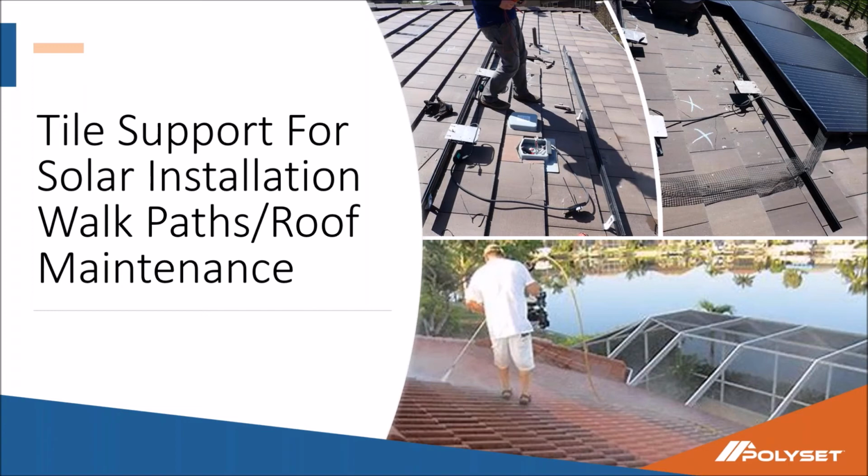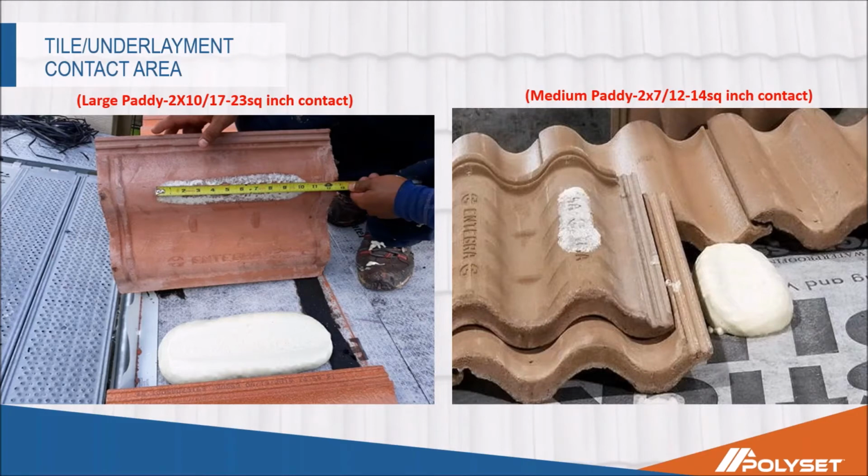Also, for those that have a solar department, we're seeing a lot of solar now evolved in various markets. We usually get a lot of calls from people wanting to use the adhesive, especially around the walk path areas of these solar panels. Also, in certain markets, you have to pressure wash these concrete and clay tile roofs due to mold and mildew. So that's a lot of foot traffic on those roofs. And again, if you have the 2-component underneath each and every one of those tiles, it adds about 80% additional break strength.